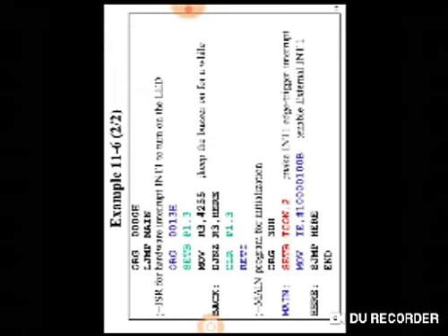If you see the first program here, it starts from ORG 0000H and immediately goes to the main program. This is usually done to organize the interrupt service routine, so that we can separate the interrupt service routine and the main program. So generally at the 0000H location we must have something to deviate our main program, usually an LJMP MAIN instruction. Once you do LJMP MAIN, the program goes to the main section. Main begins with SETB TCON.2. That is, you are setting INT1 to edge triggered interrupt, otherwise it will be level triggered.